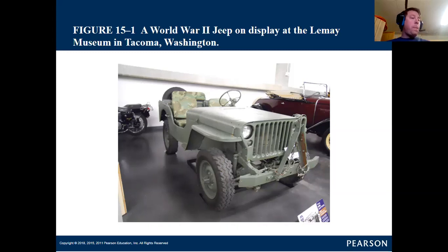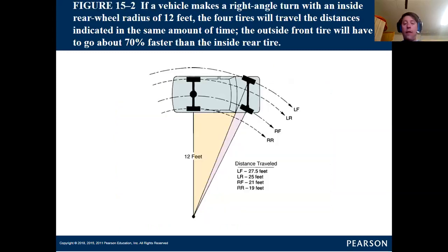So four-wheel drive vehicles have to overcome a similar situation that your two-wheel drive vehicles do, and that is while turning through a radius, all four wheels are spinning at four different speeds. Therefore, there has to be some sort of mechanism in place, like a differential, if you're engaged in four-wheel drive, in order to have equal power flow without hopping or skipping.